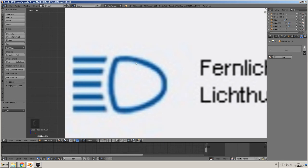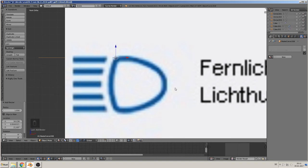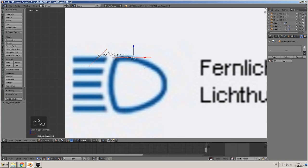For round stuff, I always take Z curve, rotate X90 degrees, scale down, edit mode, go to the lines where we want to have breakpoints. Here's the start, and it should come here. So we tweak them, then we extrude it to this part,